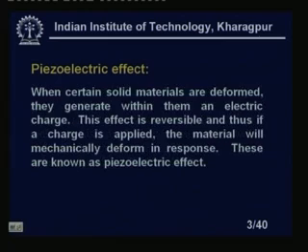What is the piezoelectric effect? When certain solid materials are deformed, they generate within them an electric charge. This effect is reversible, and thus if a charge is applied, the material will mechanically deform in response. Exactly this we did while making the ultrasonic sensors. Instead of steady voltages, we give a time varying voltage across one plate. Obviously the force you get is also a time varying signal, on the order of megahertz, so we can get ultrasonic signals from these piezoelectric sensors.